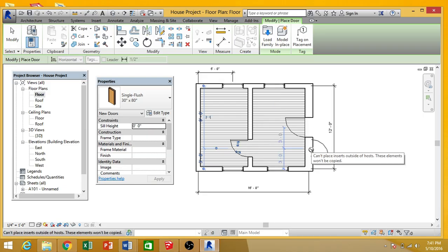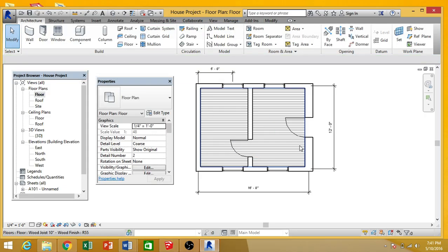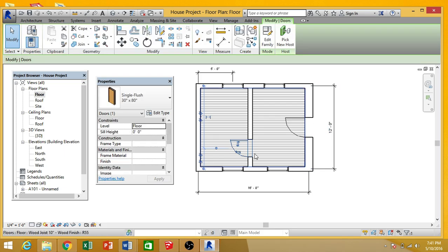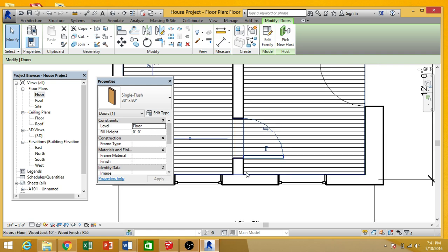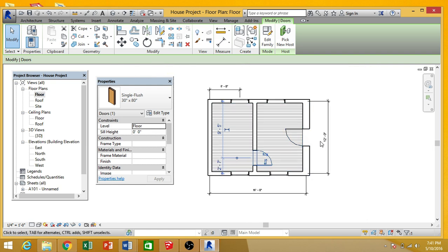And again, you want to make sure your doors swing in a certain way where it's the most easy. So, oops, I hit escape. So let me just go back and click. Yeah, I just hit escape. I went and hit modify. I'm going to click on my door. I can move my door, by the way, right here. I'm going to make it close to the wall, and I'm going to swing it the other direction and up against this side wall, so that kind of gives people the option to walk in here and then flow easily into the next room. Okay?